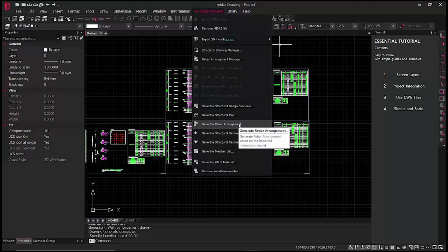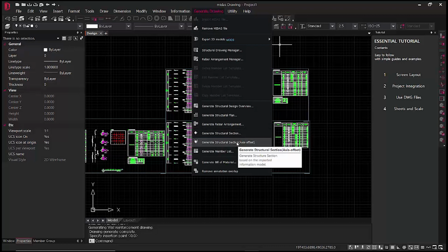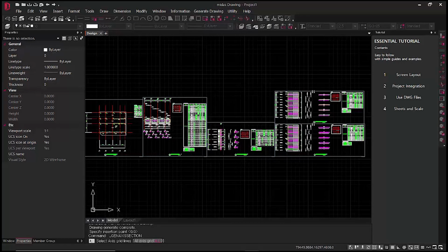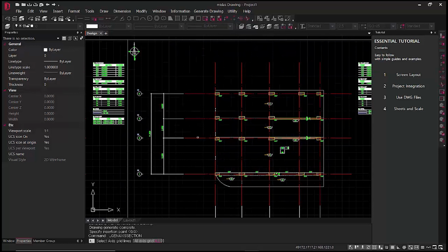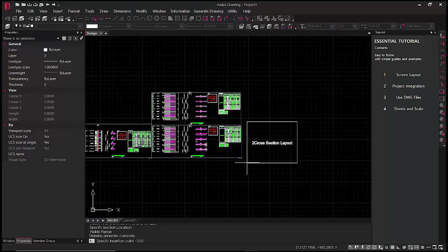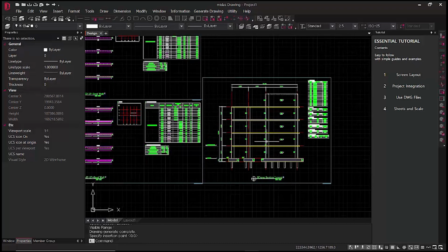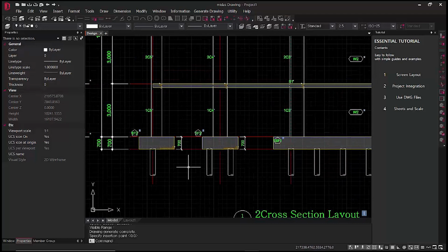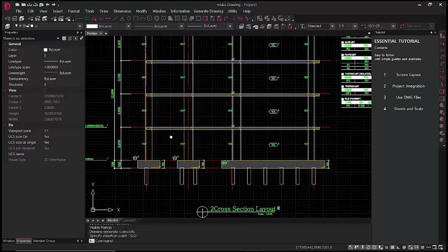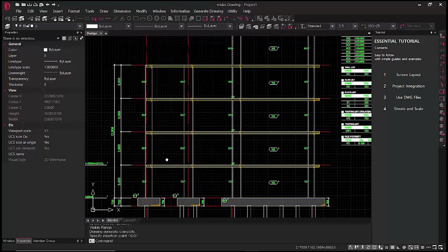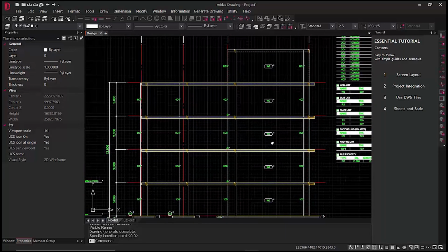There are two ways to create an elevation drawing. The first method is to select a centerline grid and directly create a selected location. Click Axis Offset and select the grid. Next, specify the visual range. Elevation drawing is always created by extracting from the floor plan. You can check the reflected shape offset and information about the pile.